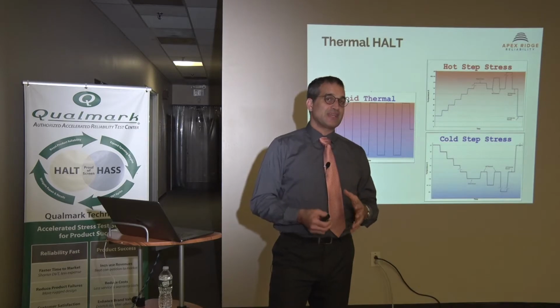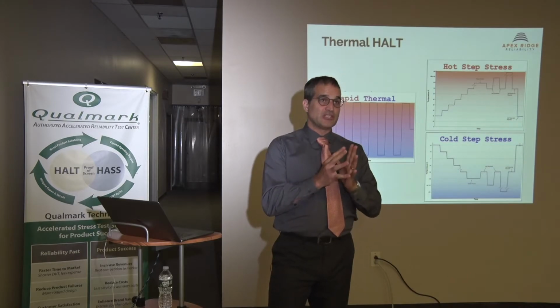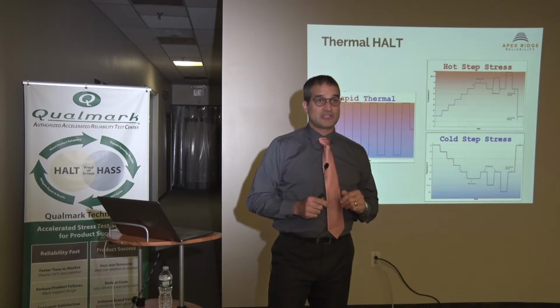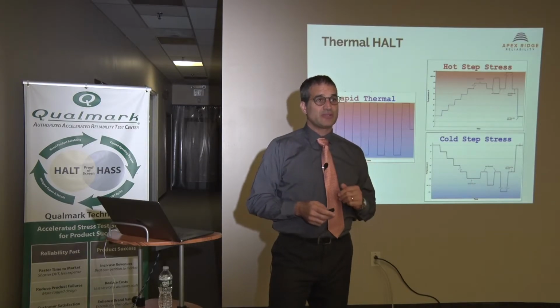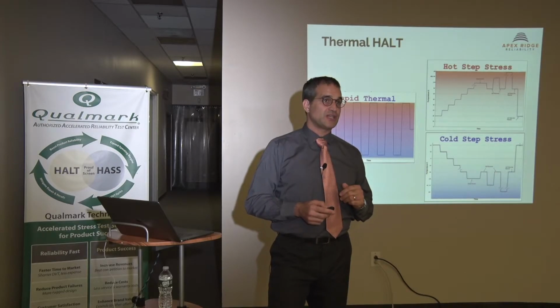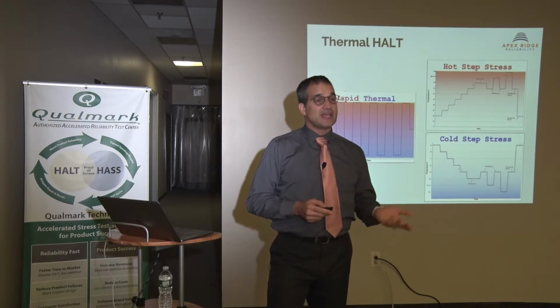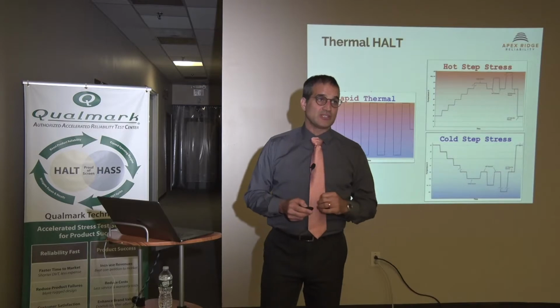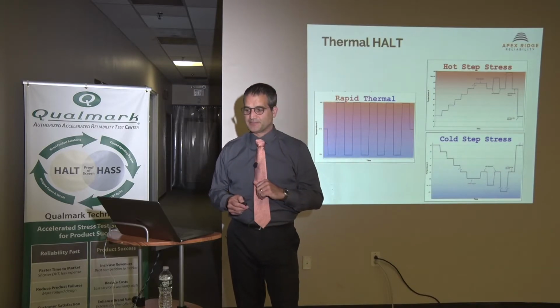We're looking to create mechanical stresses from different thermal expansion coefficients and volumes that will have a thermal gradient across it. So having liquid nitrogen is key. That's the only way you can get those kinds of fast temperature transitions. And we'll be having some talks later from some specialists with regard to liquid nitrogen and how it can be delivered effectively.